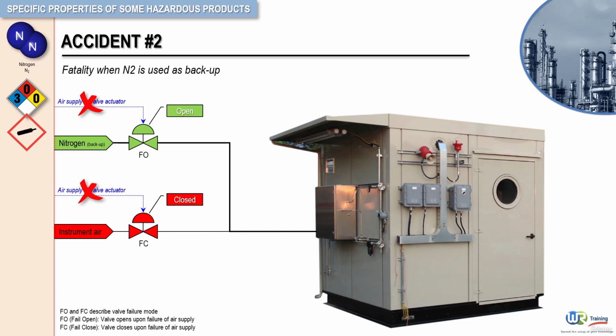In this accident, the controls and safeguards that were required to be completed prior to switching over from instrument air to nitrogen gas had not been fully implemented, one of which should have been the locking of the analyzer house doors. The design of the analyzer house permitted a nitrogen-rich atmosphere to develop by using instrument air as a purge. As a result of this administrative breakdown, the instrumentation technician was asphyxiated when he was allowed to enter the analyzer